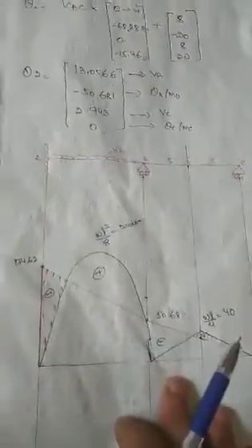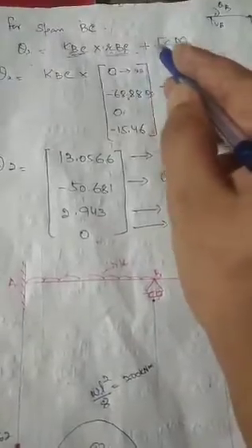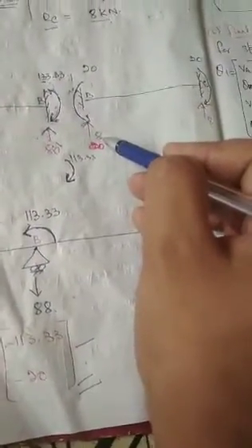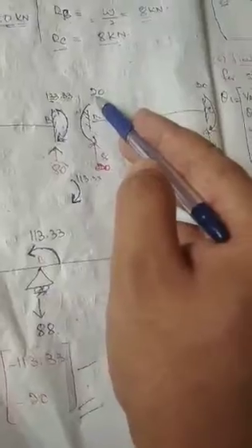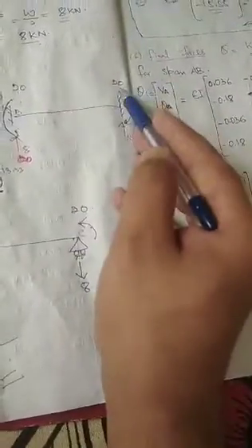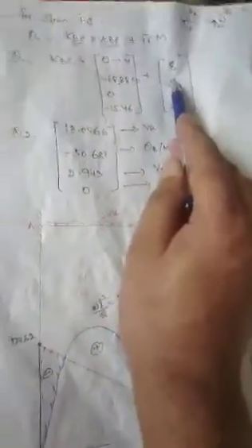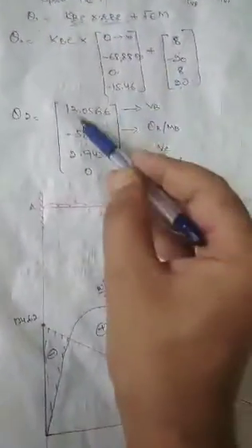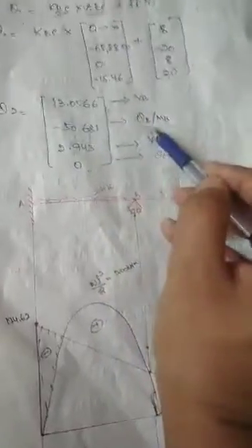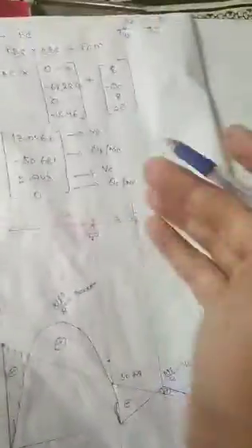You must understand how it comes. So then plus fixed end moment we will calculate the portion for BC span. Fixed end moment will be first reaction 8, then minus 20, then 8, then 20. It is positive direction. So here 8, minus 20, 8, 20. So after multiplying and addition of these three matrix, we will get the matrix VB, QB, VC, QC.